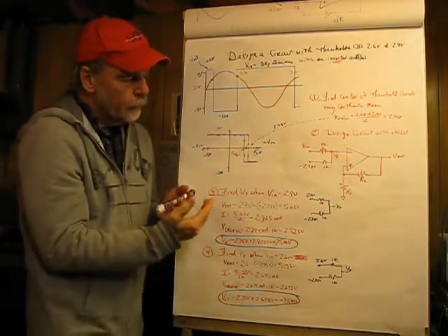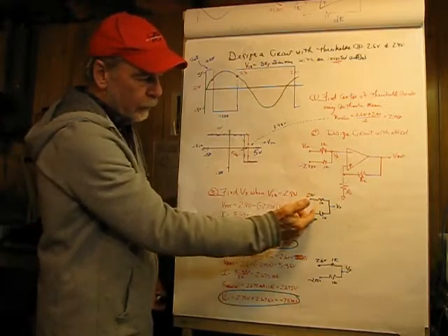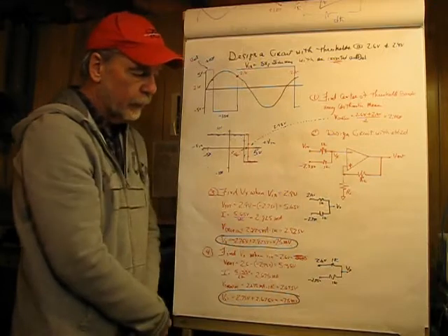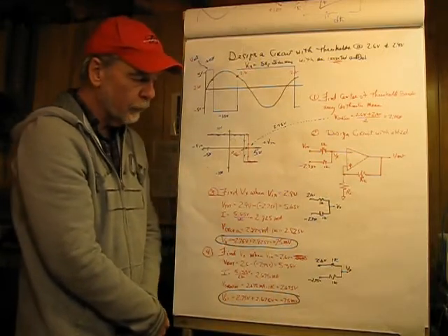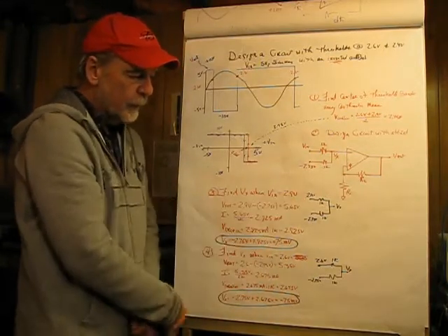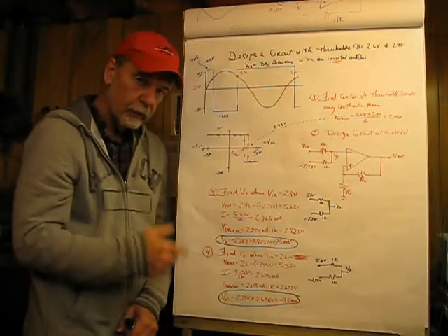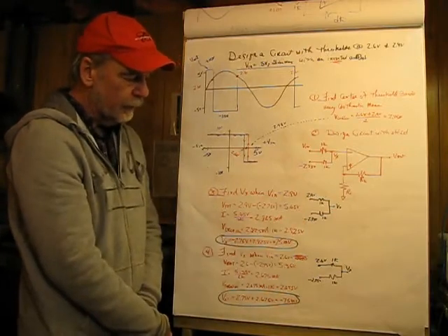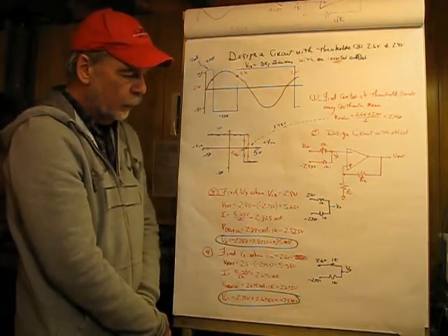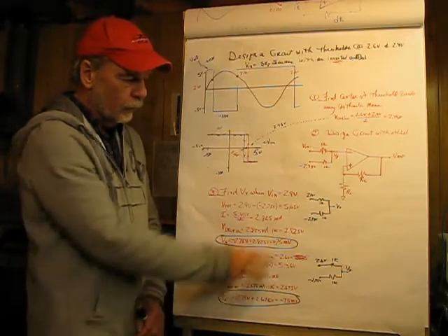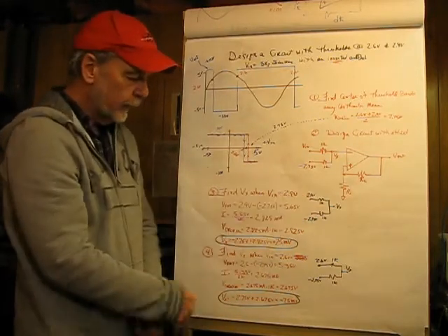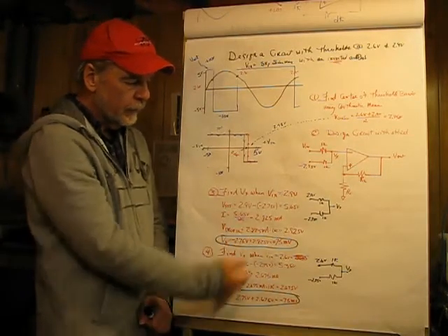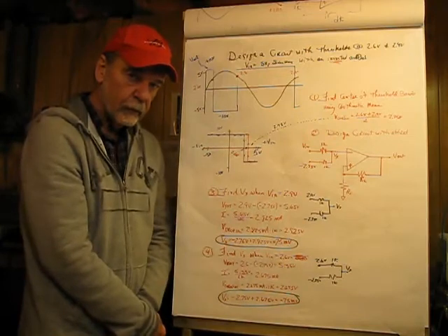To help me see this, I'm going to segregate my resistor network from my op-amp, remembering that the load from the op-amp is very low at point Vx. I'm going to let the input be its maximum threshold of 2.9 volts, and on the other side of my 1K, I'm going to have negative 2.75 volts. What I want to do first is find the total voltage across the two of these. Well, that's easy enough. 2.9 volts minus a negative 2.75 volts gives us 5.65 volts.